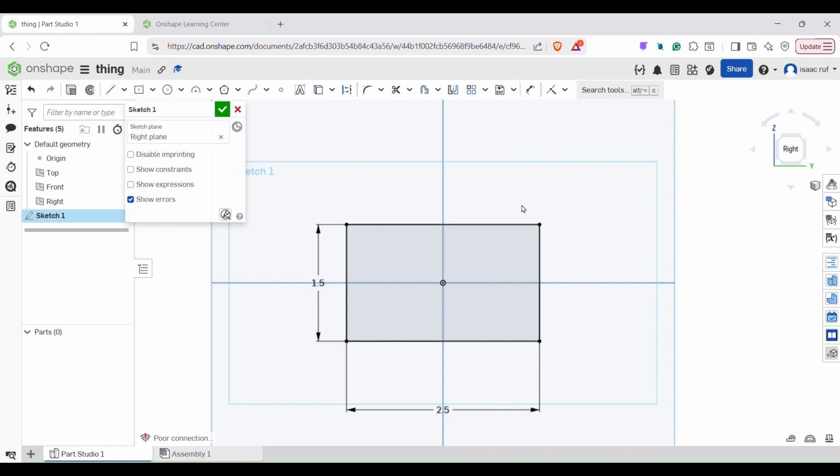This part is going to be what we'll call a motor retainer area. It'll be a flat 1/4 inch stock part, so we can make that. The first thing I'm going to do is put a hole in this part. There are two ways to make holes in flat parts in Onshape. One is when I make the sketch for the flat part, I can put a circle. I'm going to make this the size of a 1/2 inch hex bearing, which you'll see what it is later.